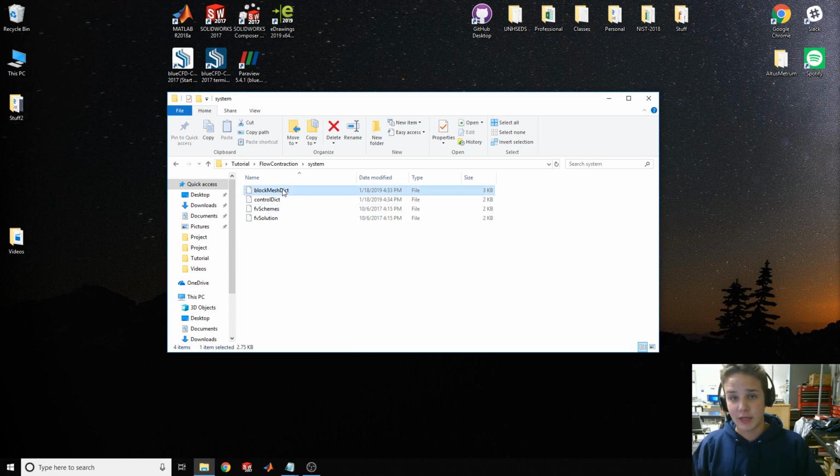So we're going to do a flow contraction. It's basically going to start with a rectangular flow coming in and then contracting to a smaller flow. A basic concept is flow, which is A times V equals A times V. If it's a smaller cross section, speed has to go faster, continuity of mass.